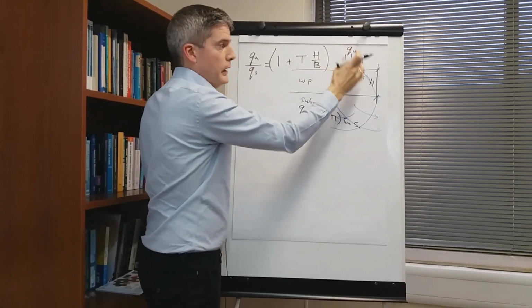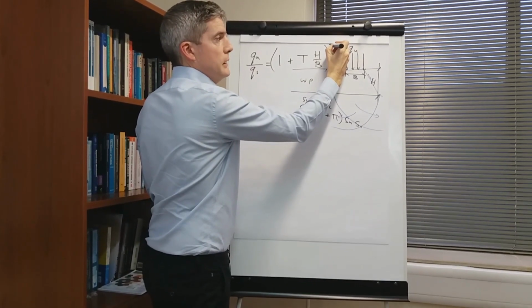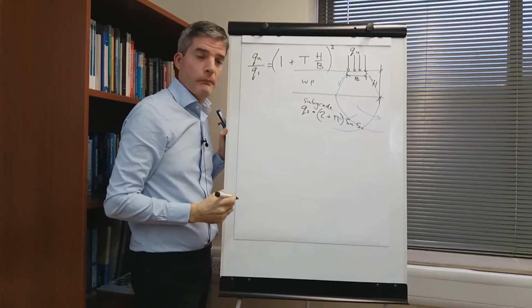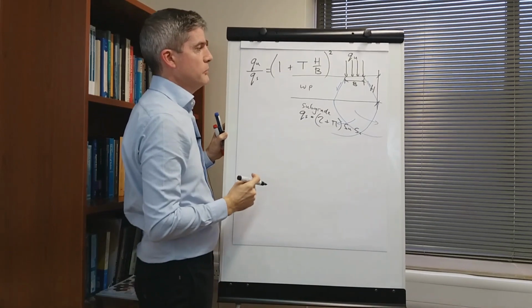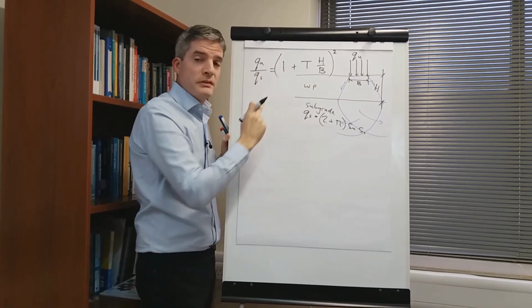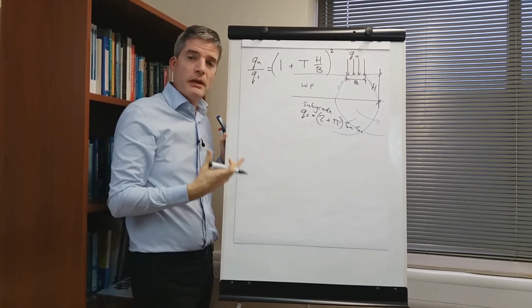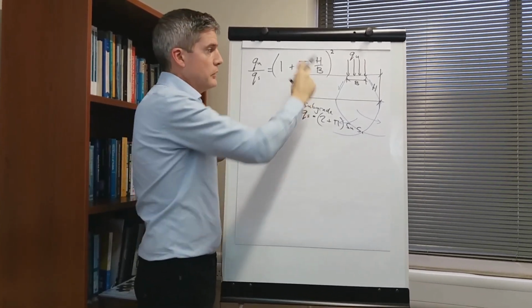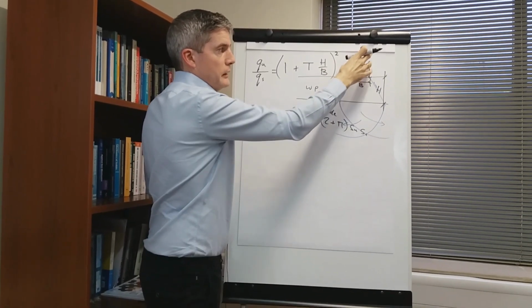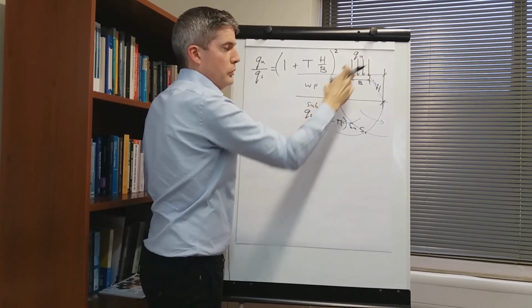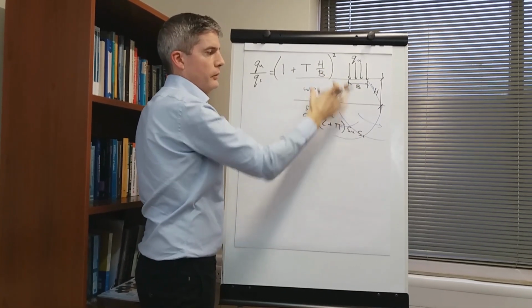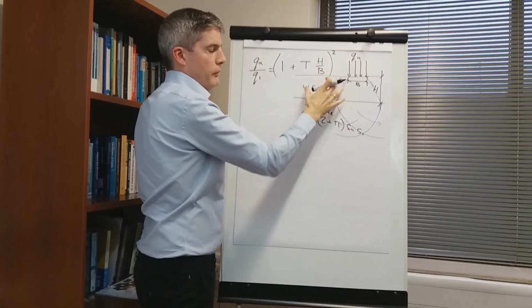If it's a square load, then you would just need the square term at the top there. So a very simple expression. Of course, you need to know what this T value is, hence the name of the method, the T-value method. It tells you how efficiently this load is transferred through this granular material to the subgrade beneath, and it depends on the strengths of the two layers.